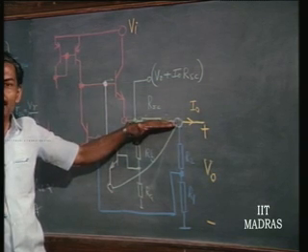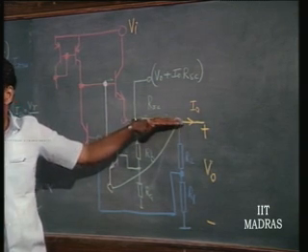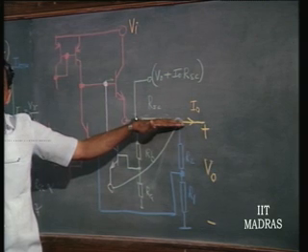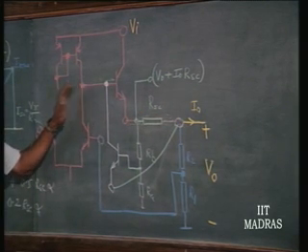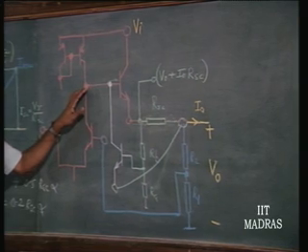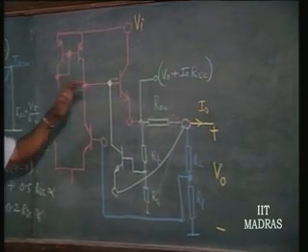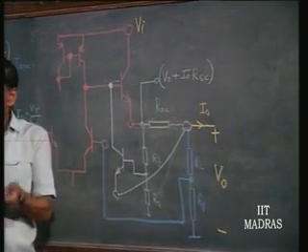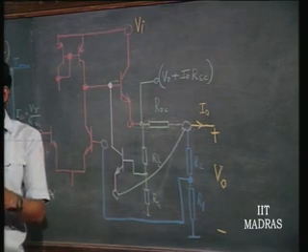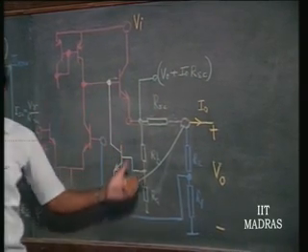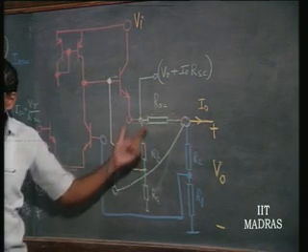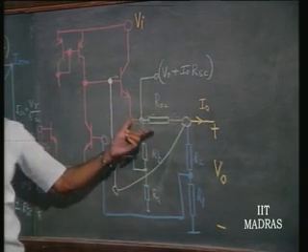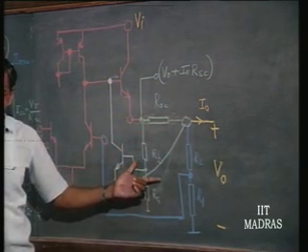Even when this is pretty high, this is not going to fix up the output impedance, because we are going to make this particular thing very high, and that divided by beta is the output impedance without feedback. With feedback, it is going to be reduced by the loop gain of this stage anyway. So, that output impedance is going to be low because of the negative feedback here.